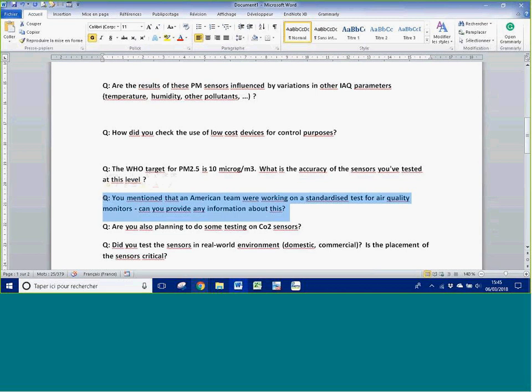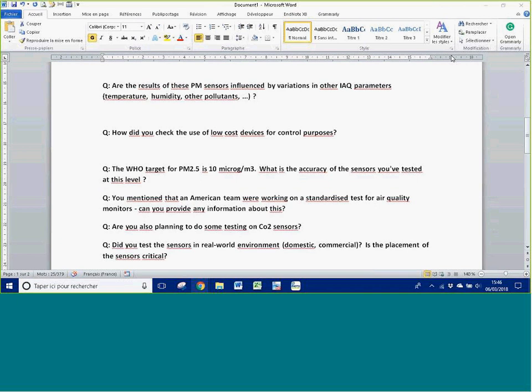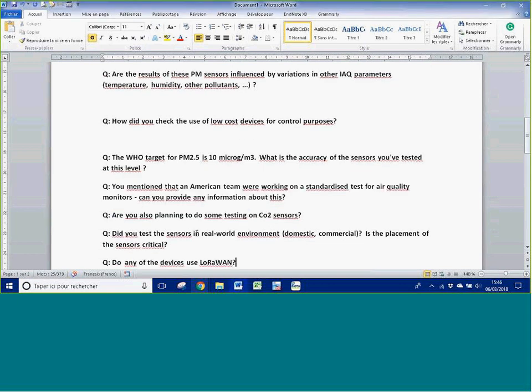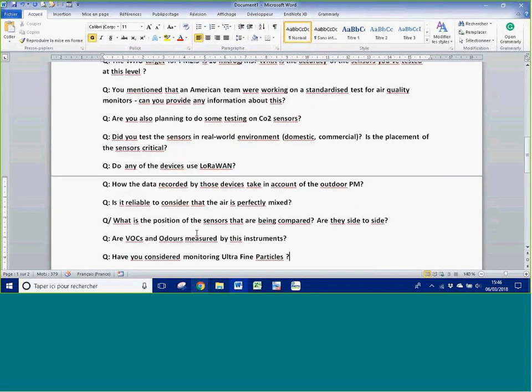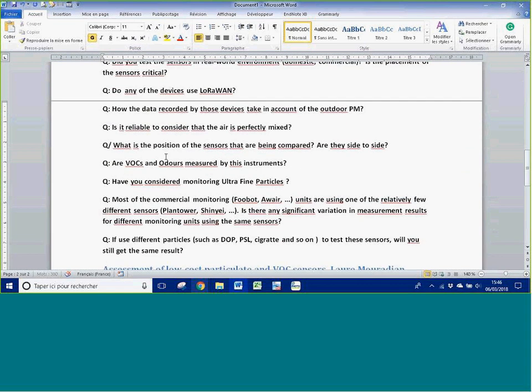And they're basically thinking along the lines of some ISO or ASTM test method where you would have specific, let's say, events generating particles of a known size distribution that you would measure with a reference device. And we would come up with a set of exposures to particles that would capture a broad range of events, similar to the ones I discussed earlier, and, we had another question there about sensitivity to temperature and humidity, so we come up with a suite of tests that encompassed a range of temperatures and humidities and different particle size distributions and magnitudes, so that let's say you came up with 20 different tests that you would run your device by, and each device would be run under all those same 20 test conditions.